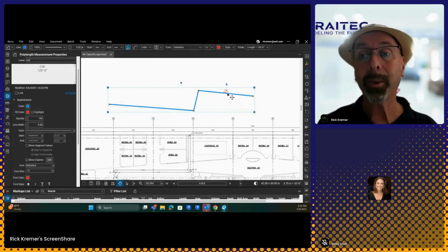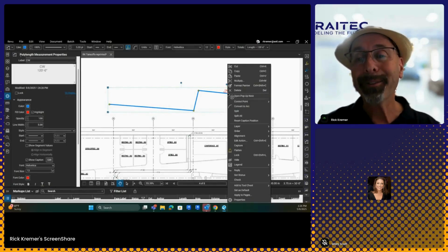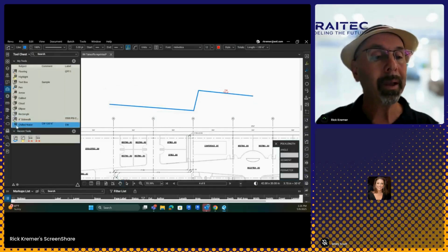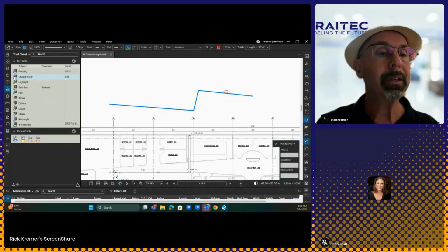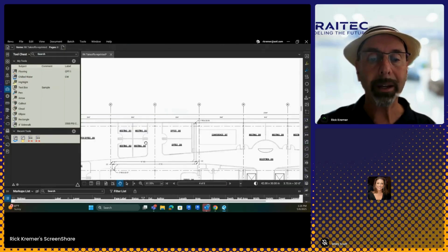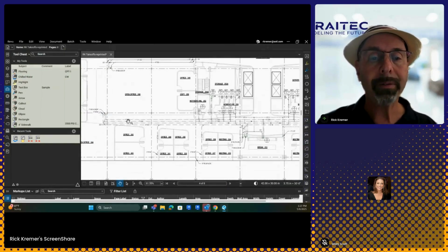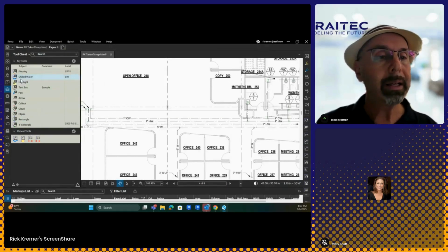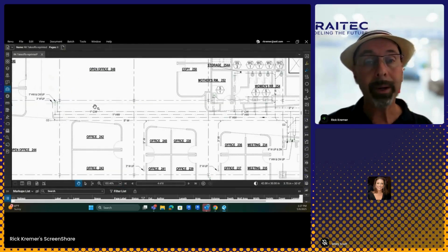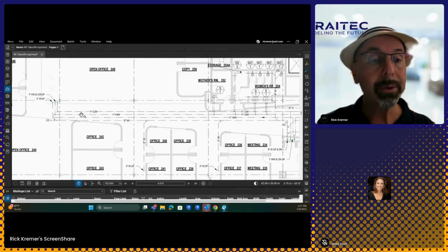So here's chilled water, just chill. I'm going to go over here and select it and add that to my tool chest, my tools. I'm going to move that over here to the number 2 position. So how do I start to go through and use that, you might say? Well, over here, I'll find my chilled water. It's number 2. Guess what? I'm going to minimize this. And because we're good, we're going to use that shortcut key of number 2.